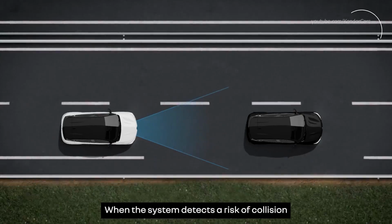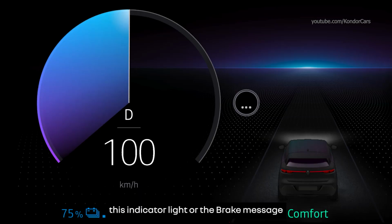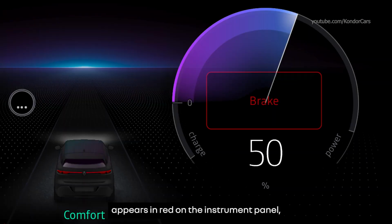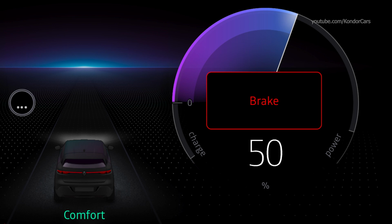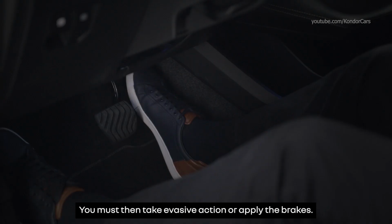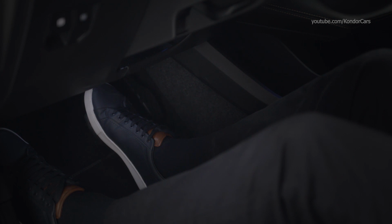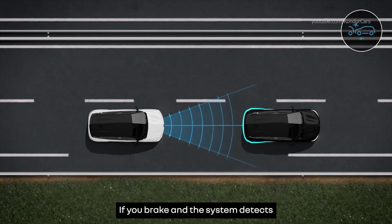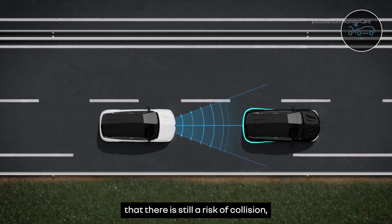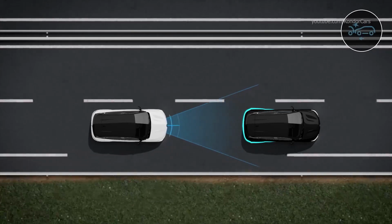When the system detects a risk of collision with the road user ahead of you, this indicator light or the brake message appears in red on the instrument panel, accompanied by an audible signal and micro braking. You must then take evasive action or apply the brakes. If you brake and the system detects that there is still a risk of collision, it will increase the braking force.